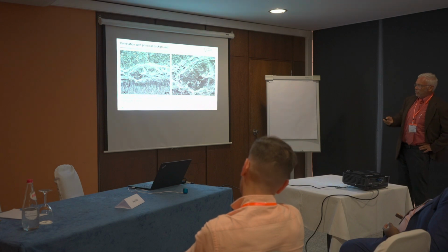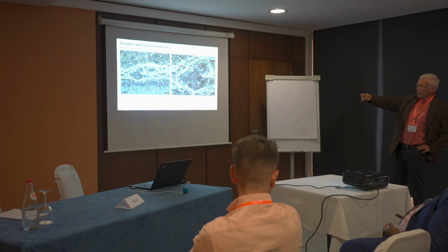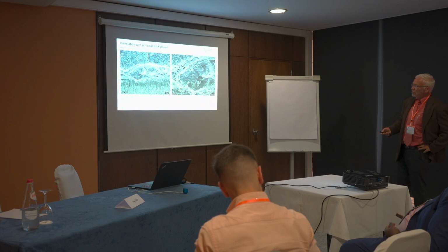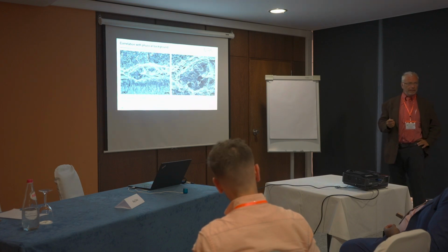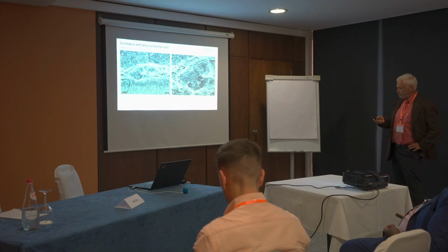This is an example of what you can see on the fracture surface of these specimens. We have the pre-cracking of the lower bottom and then the stretch zone. And what you can see is that in this region of ductile crack growth, this is an enlargement, we have some brittle fracture which stops here. We call this local arrest, because the whole diameter is 100 to 200 microns, so it cannot be seen in the global FCOD.